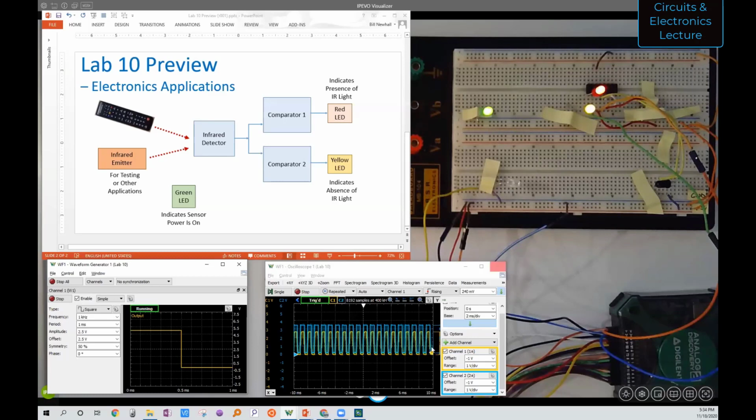What the comparator is doing is comparing the yellow trace, the voltage out of the detector, to a really low threshold, like a quarter volt. That's what this trigger is set on down here. And so you can see both lights look like they're on. Well, that's because the infrared light is turning on and off at a kilohertz, so it just looks like they're both constantly on. If I go down to, let's say, 1 hertz here.